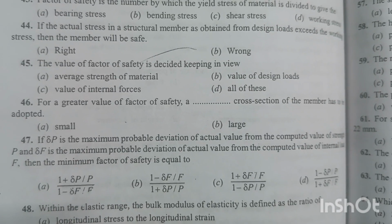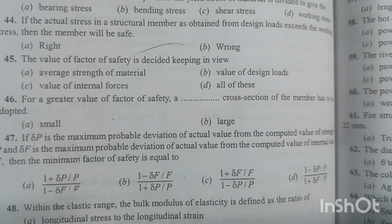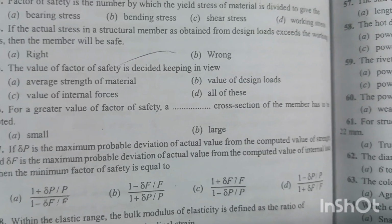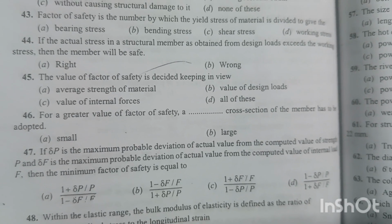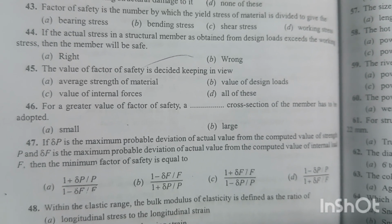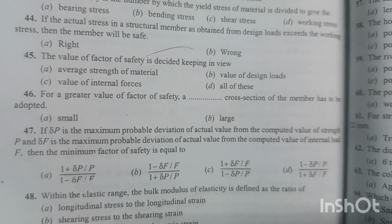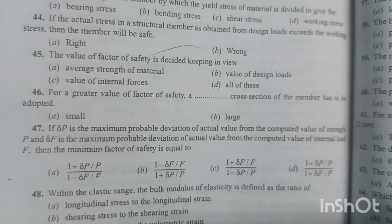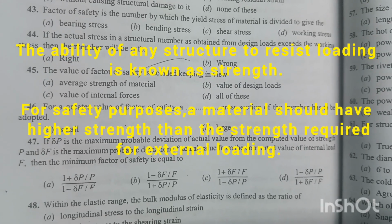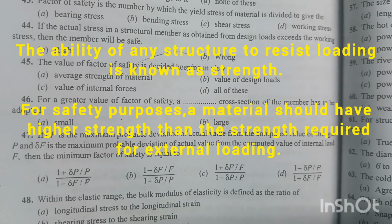Question number 47. If ΔP is the maximum probable deviation of actual value from computed value of strength P, and ΔF is the maximum probable deviation of actual value from the computed value of internal load F, then minimum factor of safety is equal to, option C is the right answer, (1 + ΔF/F) divided by (1 − ΔP/P).